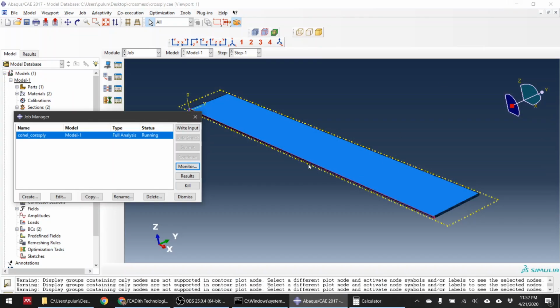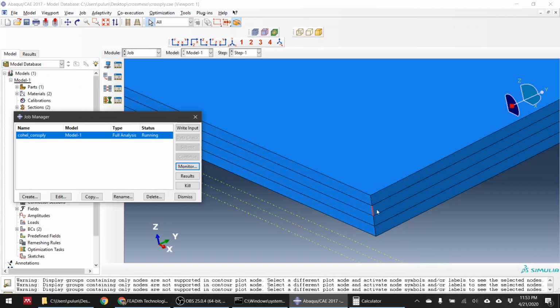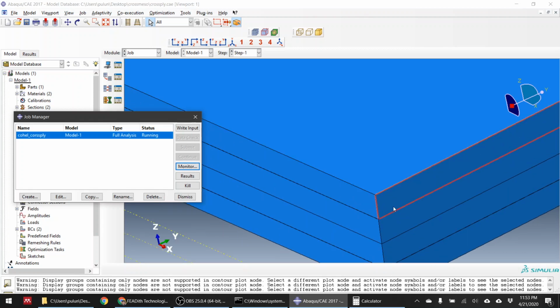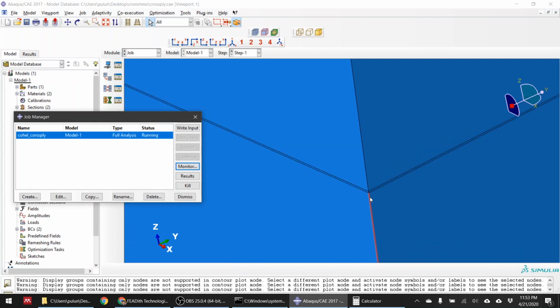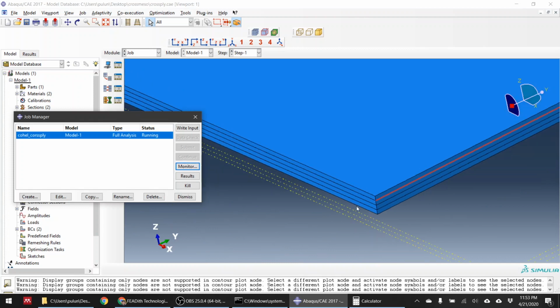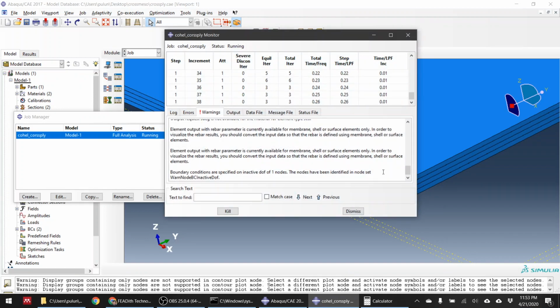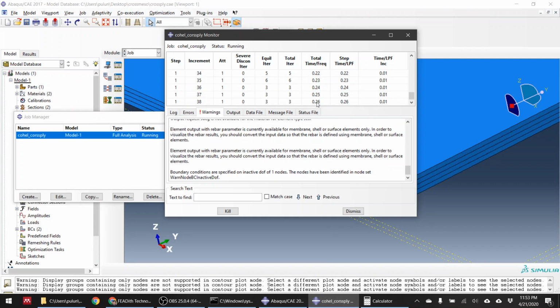All right, guys, welcome back to the video about modeling this composite laminate at mesoscale. We are modeling it using cohesive elements right now. Each ply is connected using the cohesive elements, like this one, to facilitate delamination between the plies with different orientations. It's still running actually. My computer is not really a good computer, it only has two processors for threads, so it's quite slow. But now it's already about 25% of the total time that we assigned to the problem. The total time is around one.